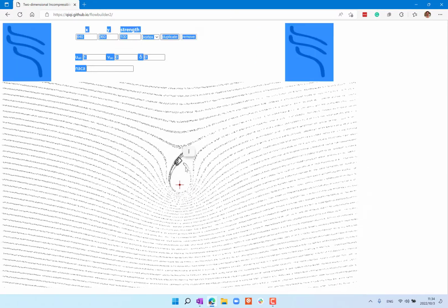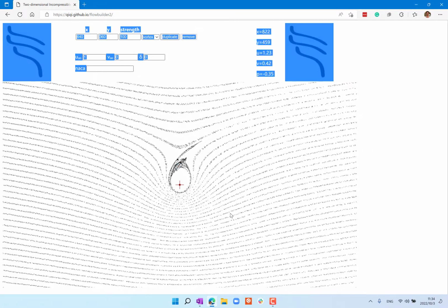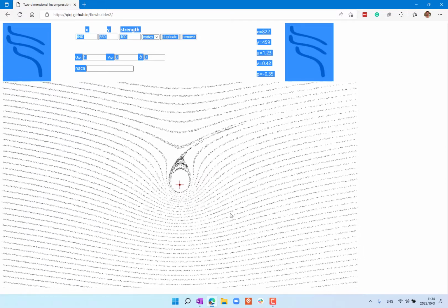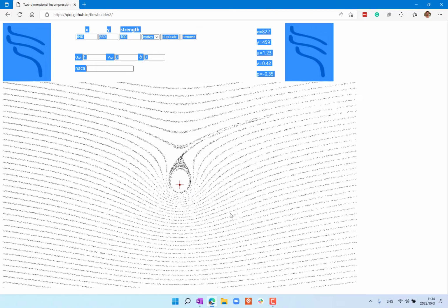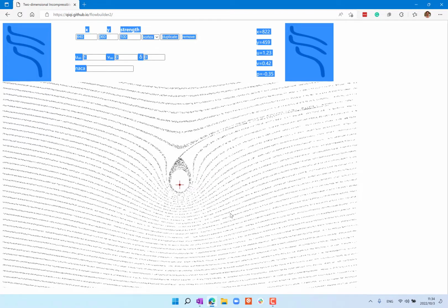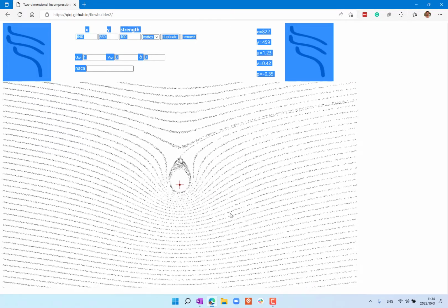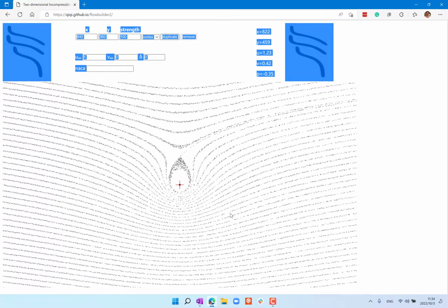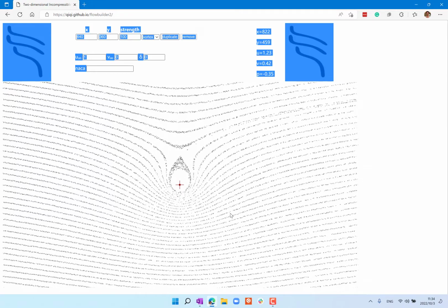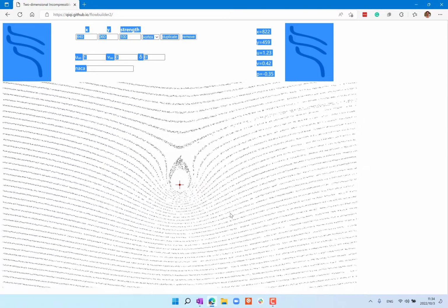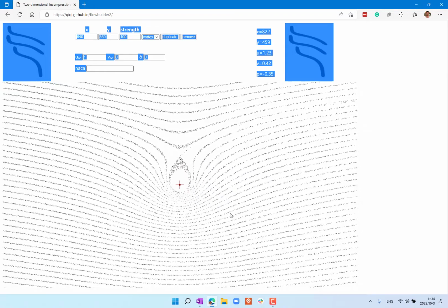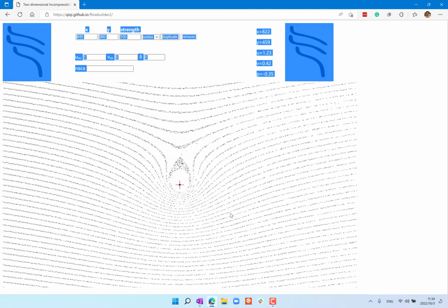For example, if you see a lot of additional particles inside this region, you can visualize what this kind of airfoil at minus 90 degree angle of attack is like. You can start to see this solid shape. And as I said, the flow field near the vortex would not be a physical flow field, right? Because here the vorticity is not zero. You are adding two flow fields. It doesn't satisfy the momentum equation. But if this is actually a solid body, then the flow outside of it is completely fine, right? They satisfy all the equations you want.